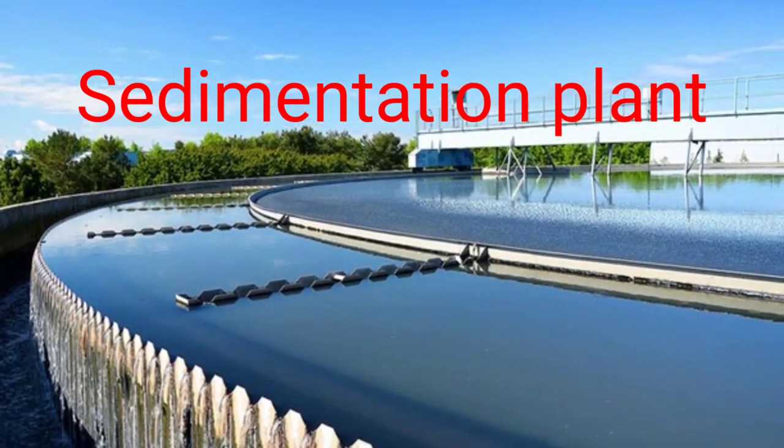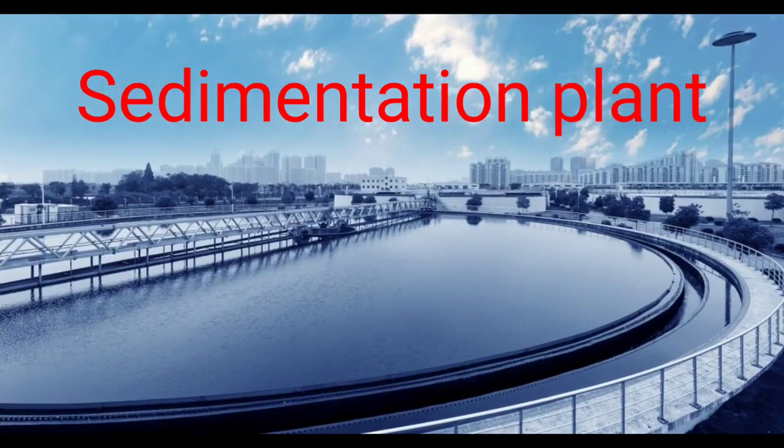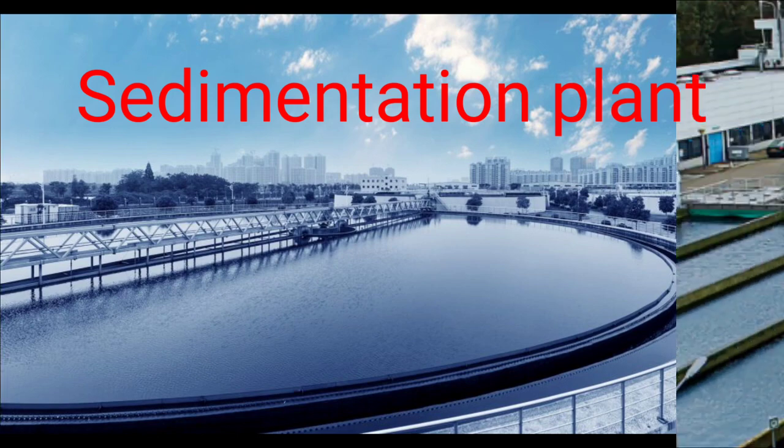The velocity of the water is lower than the suspension velocity and the suspended particles settle out of the water due to the gravity process, settling down at the downward part. The process is also known as settling or the clarification process. Settled solids are removed as sludge and floating solids are removed as scum. Water leaves the sedimentation tanks over the effluent weir to take the next steps of the treatment.